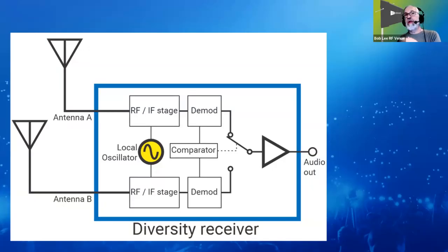Multi-channel systems will use a distribution system, or distro, that is essentially a dual distribution amp for RF that splits the two input signals from the antennas and sends them out to multiple pairs of outputs to feed your multiple receivers. Now, most digital systems also use diversity, but in possibly varying ways.